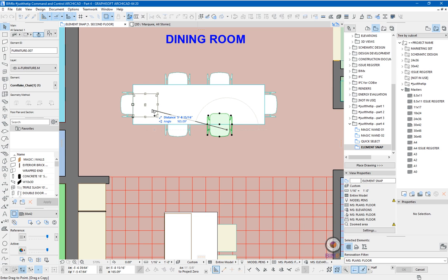If I go to a busier part of the drawing though, so maybe about there, what it's actually showing is that I've got one snap which is active right now, which is the bold one. There's also another possible one in the lower left corner, and if I press space, I can actually toggle between these.